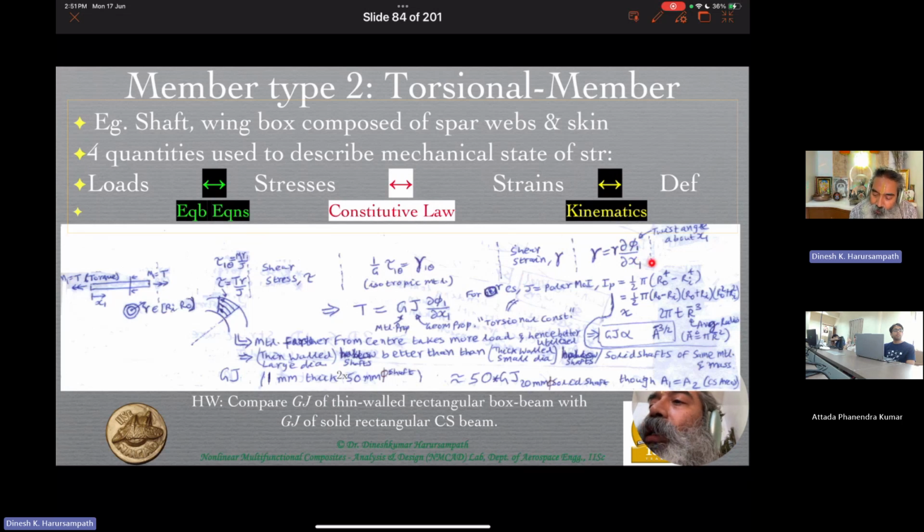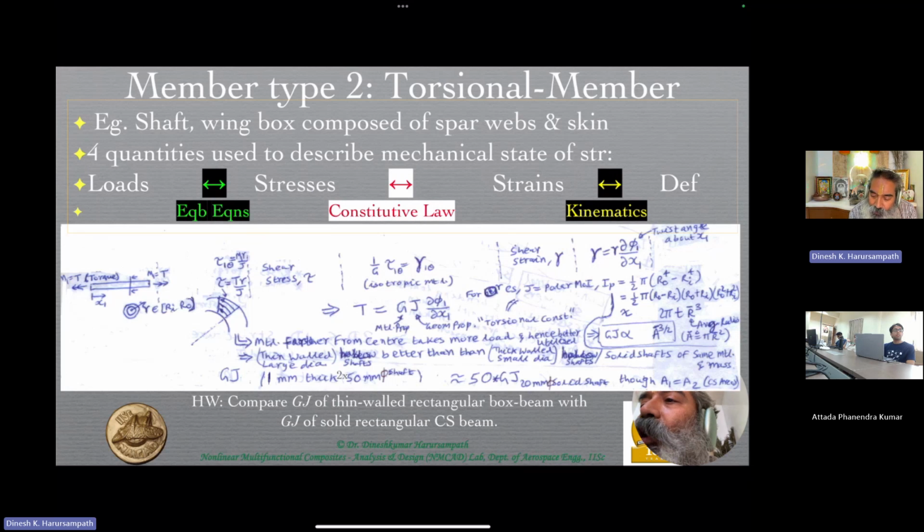The last thing is again a purely geometric relationship, where we are saying that the shear strain, remember, is nothing but the change in the right angle. And we also know from the definition, even though this is a gamma 1 theta that we are talking about, that gamma 1 theta is equal to its complementary shear strain, namely interchanging the subscripts, gamma theta 1.